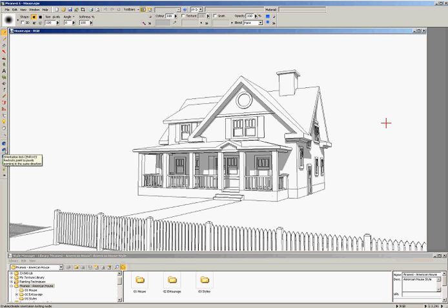The orientation lock is everything that faces in a particular direction, regardless of which plane it is, as long as it points in the same direction. And a material lock. A material lock is probably the one that gets used the most. So you can say I want to only paint a particular material on which I first click. But these can actually be used in conjunction as well, so you can have combinations of these. Color lock obviously is fairly self-explanatory. It locks to a particular color to provide any action or function.